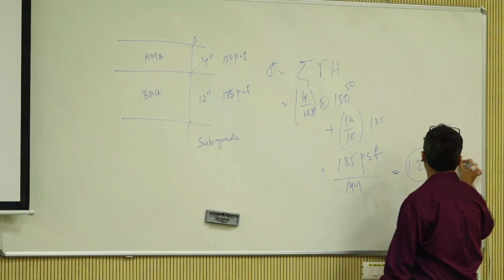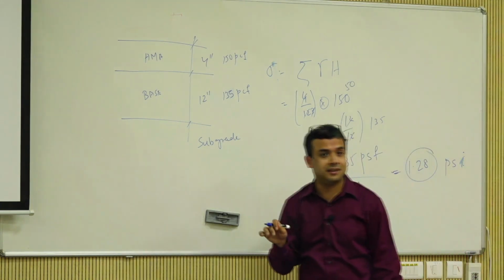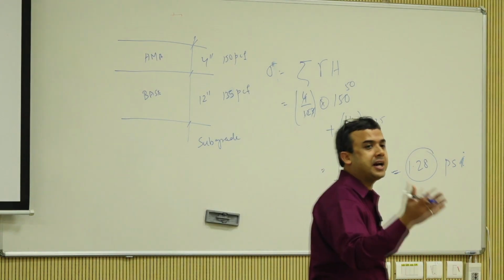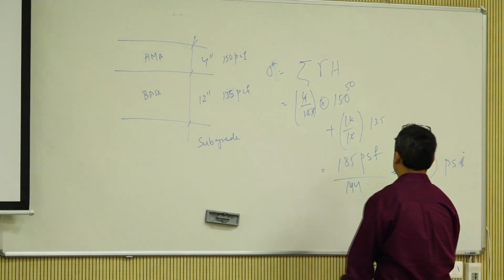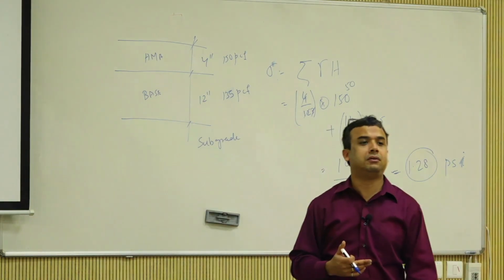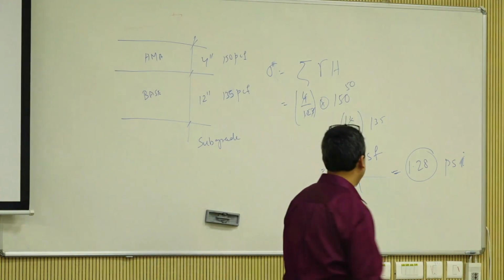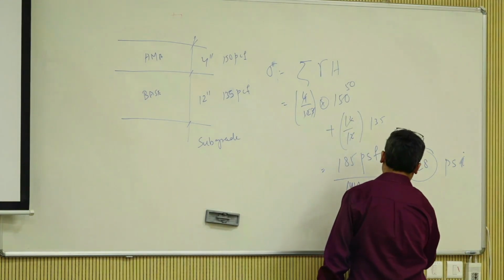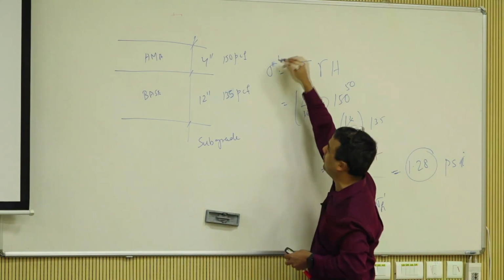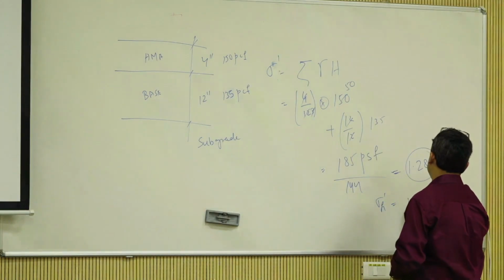0.28 psi is the vertical stress on top of the subgrade because of the surcharge, right? What is a typical K0 value? Give me a typical K0. 0.33, 1 over 3. Very good number, right? Sigma H prime. By the way, I should not write it as sigma because it's kind of wrong, because it's effective stress, but I'm ignoring pore water pressure. So sigma H prime is 1.28,